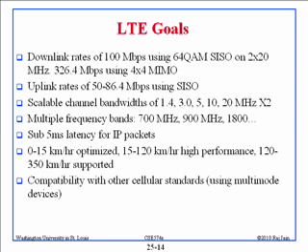For example, when we are at low speed, we get some number, and when we are at high speed, we get some number. So what makes it different? At high speed, you will have Doppler, you will have intercarrier interference, and then your data error rate will be higher, so your effective rate will be very low, to the point where it becomes zero if you are running at 350 kilometers per hour, because your error rate is 99%.